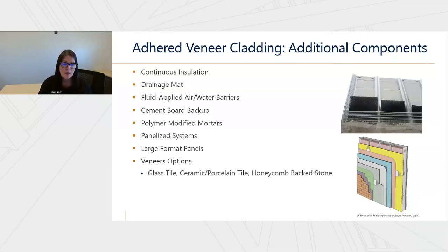We want to make sure that all those ridges are collapsed and there's full contact between that adhesive mortar and the backup. And then just the different veneer options that are available now, like glass tile, ceramic, porcelain tile. We've even seen honeycomb back stone that is in an adhered application in interior applications.